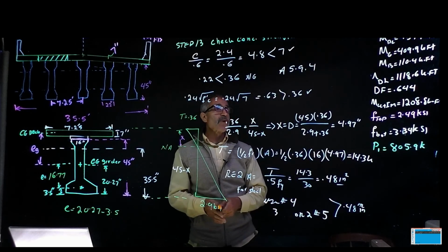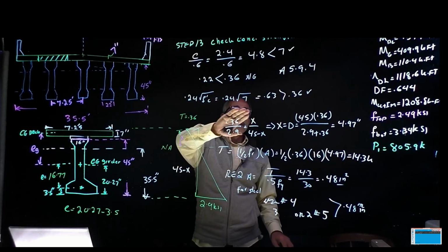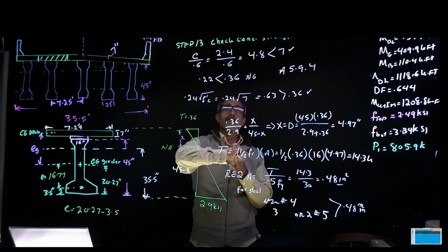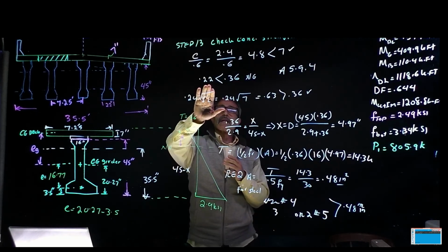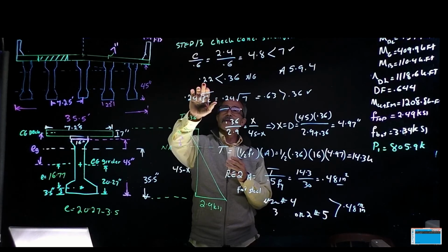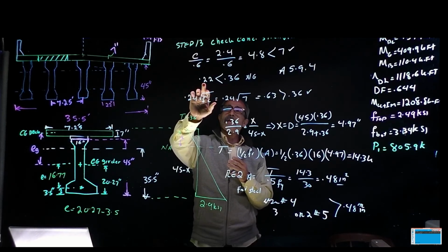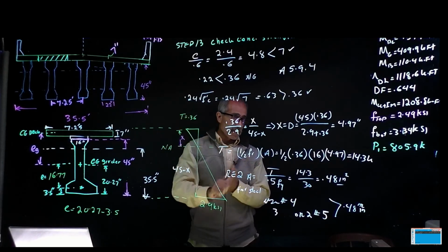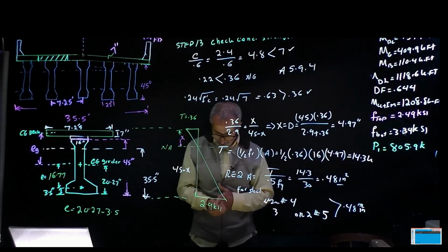So that's why in here it failed, because our tension was more than this here. So that's why it failed. So we got to make up for it by adding more rebar to it. That's not a problem. All right, let me erase this.